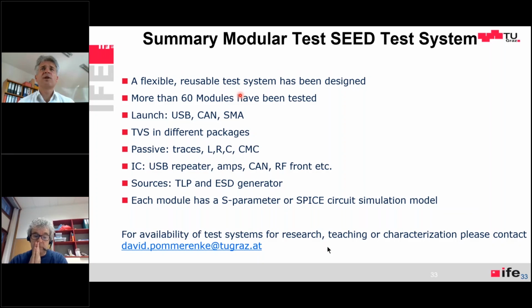I don't know if that is in the circuit diagram. In our simulation diagram, we still have a switch that is used in LTSpice, but you can also exchange the switch, which is a good way to do it, by a voltage source that will be triggered at a certain time.